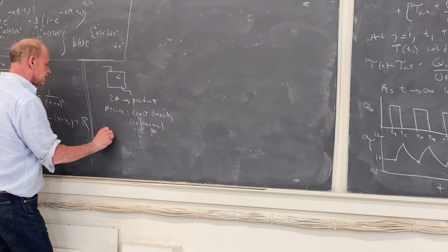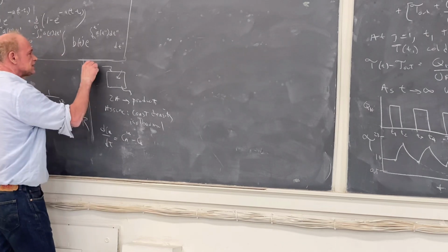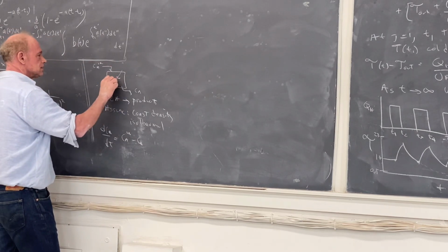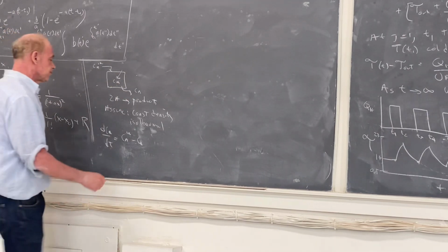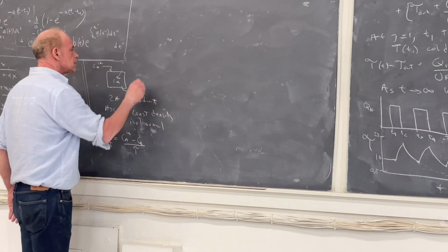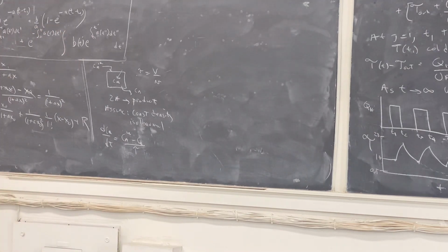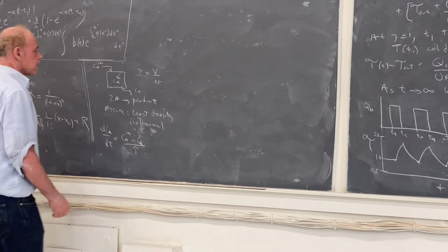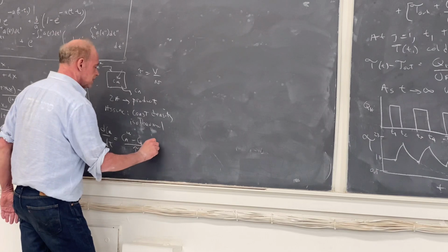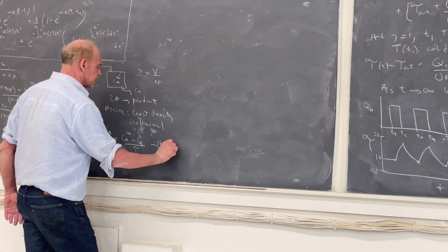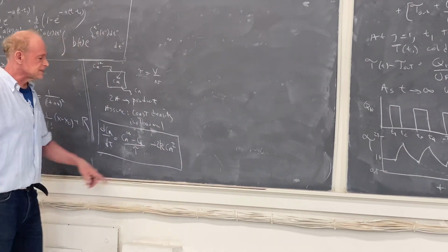I've got dCA/dt is equal to CA in minus CA. This is CA in. This is CA. Since it's well mixed, CA on the output is the same as CA in the reactor. Divided by tau. Tau is the volume over the volumetric flow rate. Plus the rate of generation, but the rate of generation is minus 2K CA squared. So here is my CSTR equation. But this is nonlinear.